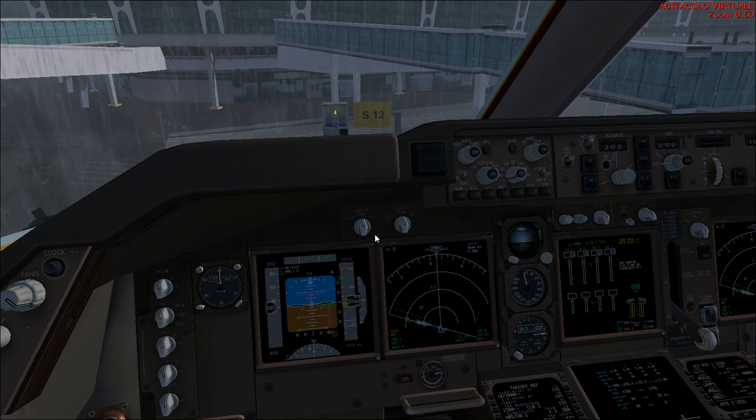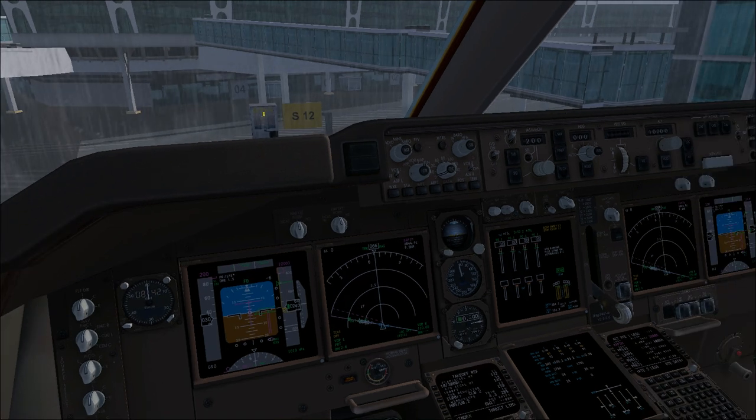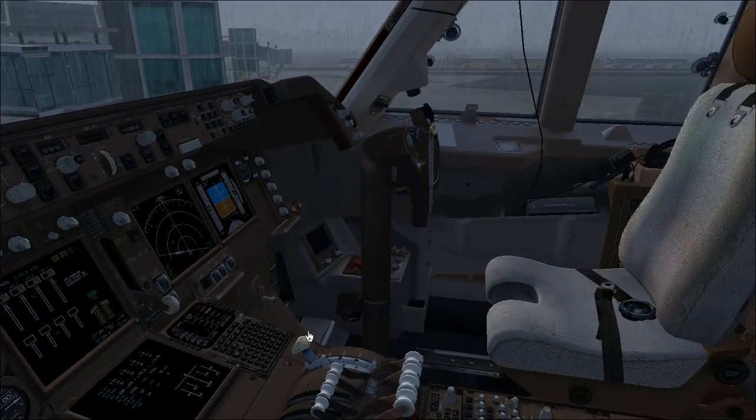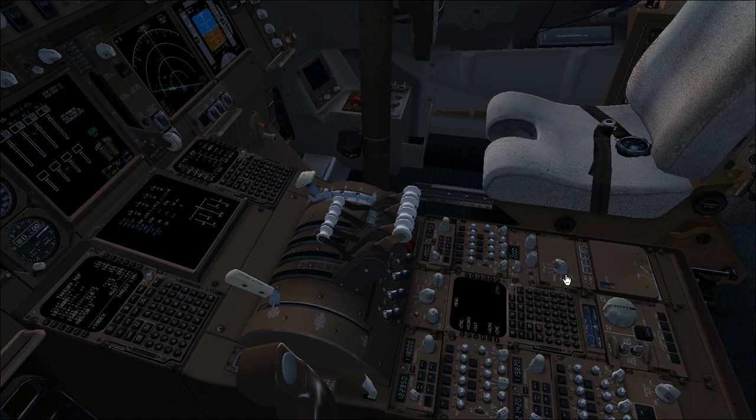Again, you have to finish the CDU preflight at this point. If you didn't finish yet, you check the instruments in the same way as before, so you check our indications are correct and takeoff and no-V speed flag, and you check again the flight director FMA indication blank, TOGA with flight director, and we display the map mode. Auto brakes must be on RTO, so we can check it. Auto brakes are set on RTO.